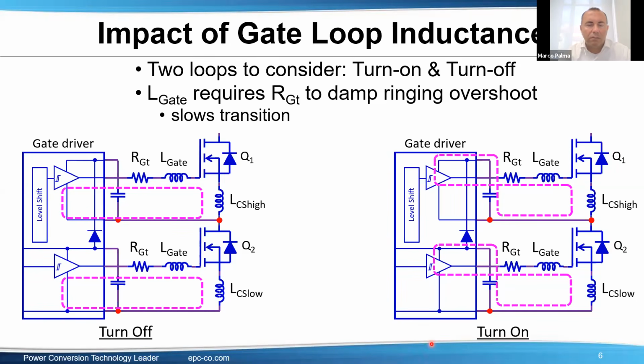It's always difficult. Are there any plans for EPC to integrate the gate driver with the power FET, as it would reduce the gate loop inductance even further? Yes, absolutely. We did it. We actually have different integrated circuits, both low side with the gate driver inside, and also a full half bridge, so high side and low side, with both the low power and high power GaN FETs.